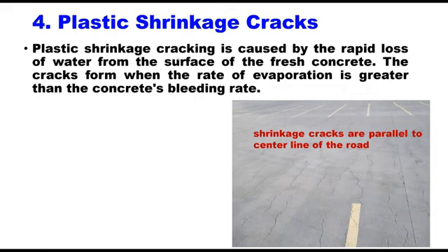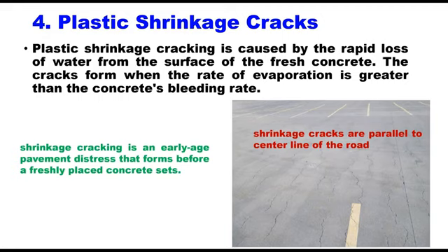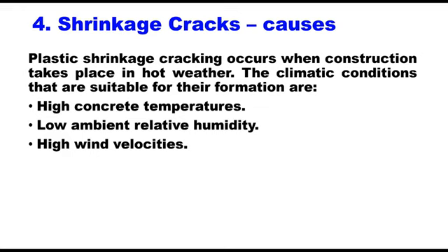Plastic shrinkage cracks. These cracks are caused by the rapid loss of water from the surface of the fresh concrete. The cracks form when the rate of evaporation is greater than the concrete's bleeding rate. These cracks are formed when concrete is still in plastic state, and that is why they are called plastic cracks. Plastic shrinkage cracking occurs when construction takes place in hot weather.